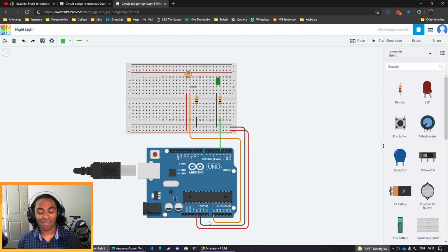If I'm using a completely analog measurement tool, something like an analog multimeter, in order to determine the voltage difference between these two signals, then I'll be able to tell it's this minuscule amount. But on something like an Arduino, these analog pins, between the actual pins themselves and the processor that's on board, go through something called an ADC, an analog to digital converter.